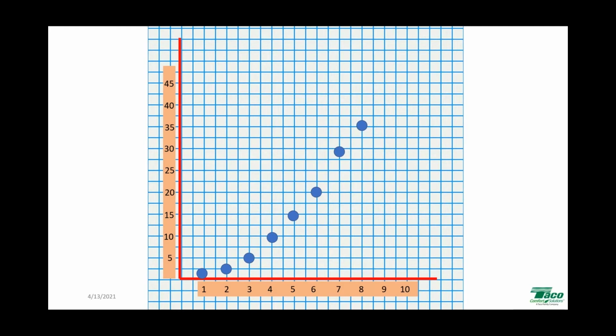Because what we've done here is we've laid out, without the pump curve, the system curve with all these different points, and we simply connect the dots, and there's your system curve. All right, and your system curve exists in perpetuity for that system, because flow and head are directly related.